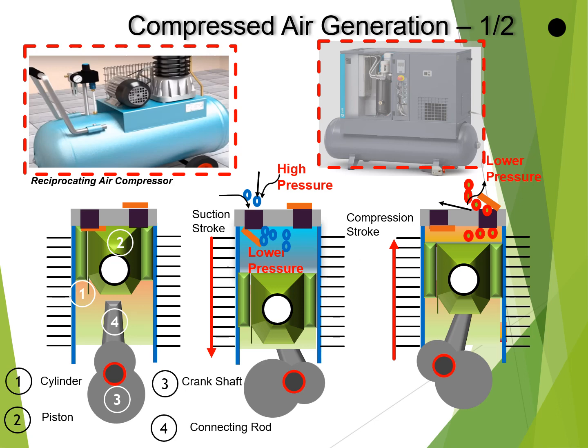We can achieve higher pressure from multiple stage reciprocating compressor. The temperature of the compressed air is better managed in multiple stage compressor as the intercoolers are provided between the stages. For example, the desired pressure is 8 kg and there is a multiple stage compressor. So maybe in the first stage the compressed air pressure is 4 or 5 kg only.